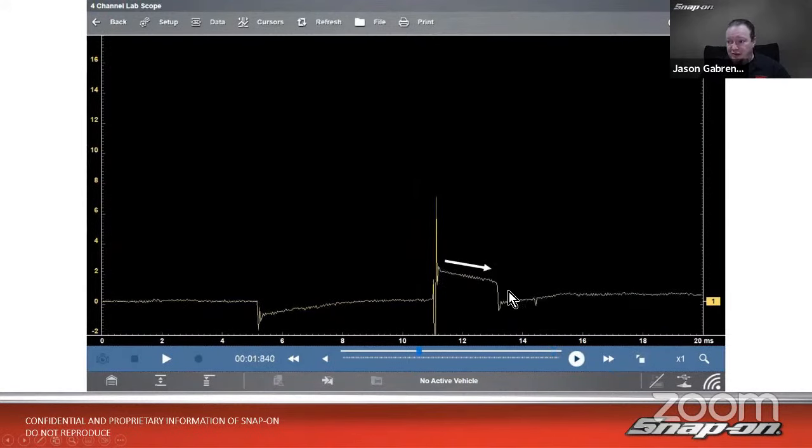This one is actually straight. It kind of looks like it's going downwards because that's just probe placement and how the probe works on this particular coil, because it's not a traditional design. It has the igniter inside of it and everything, so it's more of a modern coil. So you're not always able to get perfectly flat lines, but you just want to see, is it straight?